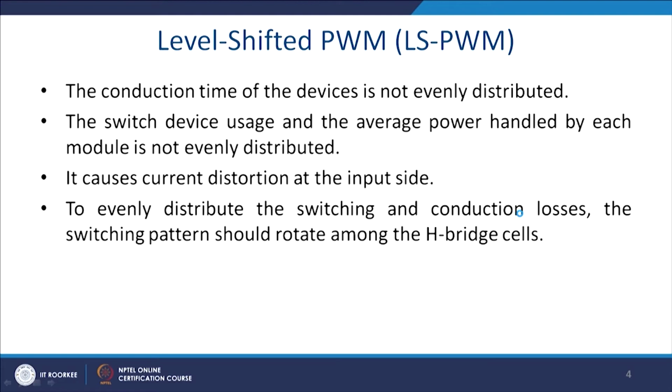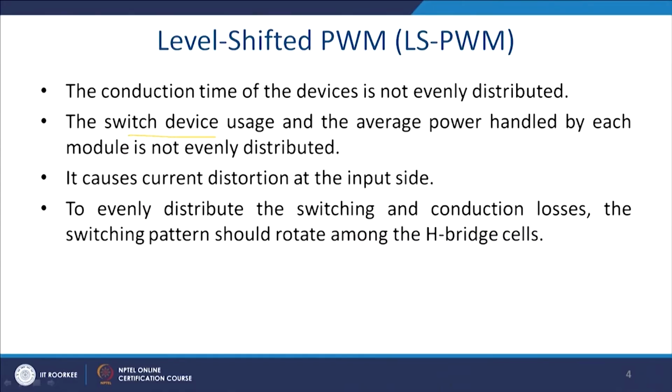Conduction time of these devices is not continuous and it is distributed among the switches. So, the thermal rating of these devices can be improved, and we can use their thermal rating optimally. The second conclusion is that the switch devices and the average power handled by each switch module are not evenly distributed. This is one of the disadvantages, and we need to manage it as much as possible by the control logic,